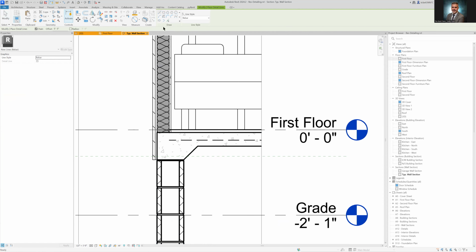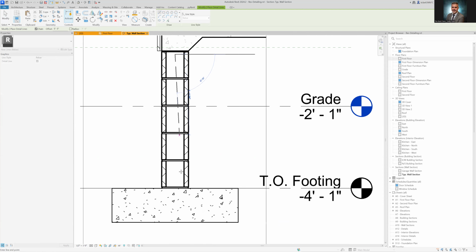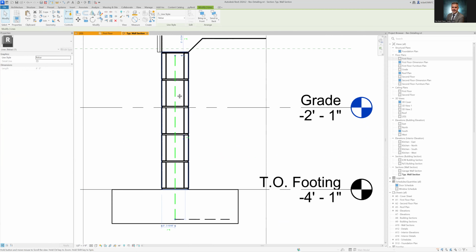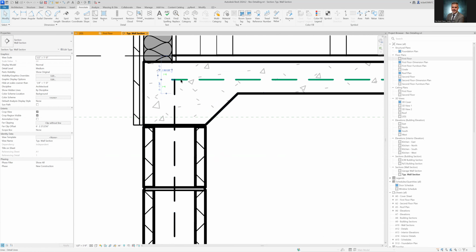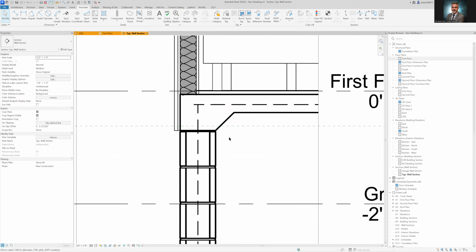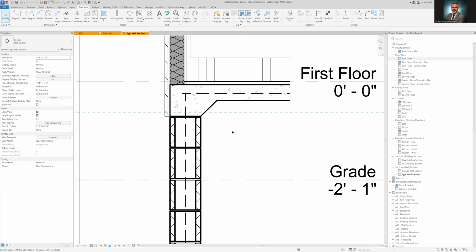All right, the next thing is you're gonna put in another piece here, and since it's possibly down the middle, you could use that snap line that's helping you out. And then it's gonna come off to the right here. All right, and then this guy is actually going to go into this as well. Okay, I think this goes a little bit further, yeah. And then we'll get a J-bolt and we'll get some studs for the base down here to put in here too. They do work off of draw orders, so keep that in mind. Let me get one more family here.